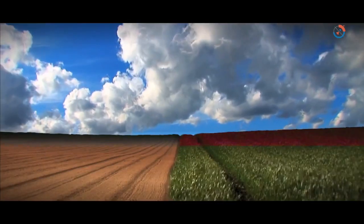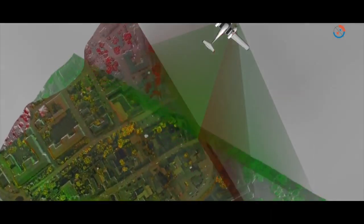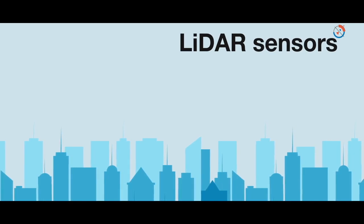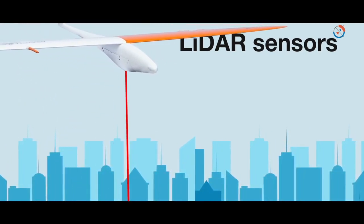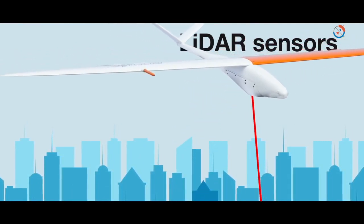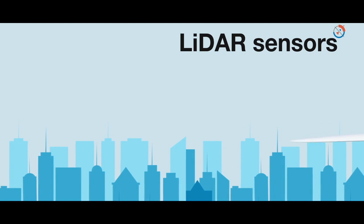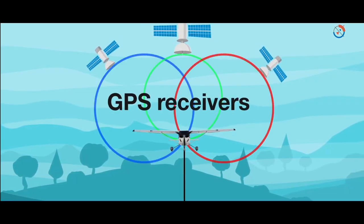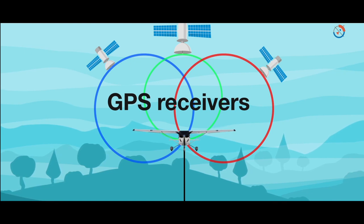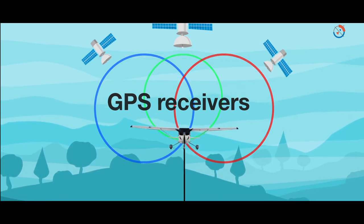How does a light detection and ranging system work? There are 4 parts of an airborne Lidar. Lidar sensors scan the ground from side to side with a pulsed laser beam as the plane flies. The sensor has a detector for sensing the returns from objects. GPS receivers track the altitude and location of the airplane. These variables are important in attaining accurate terrain elevation values.